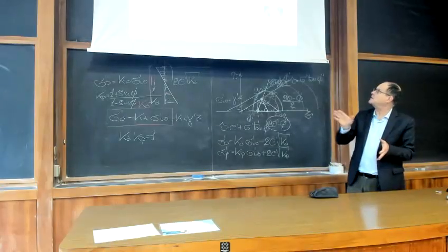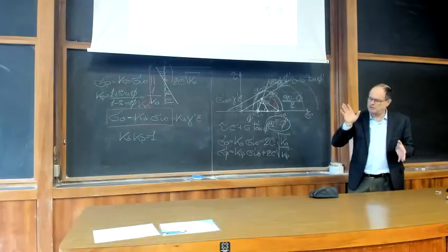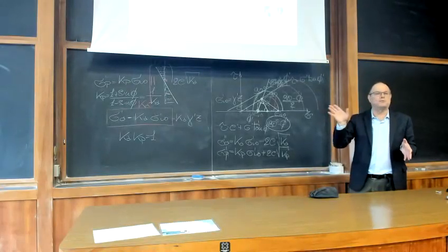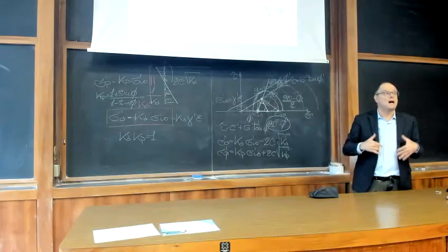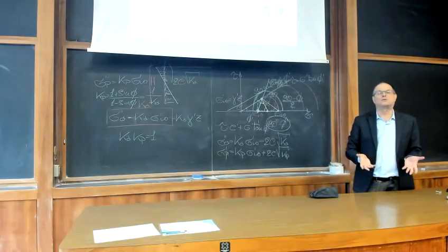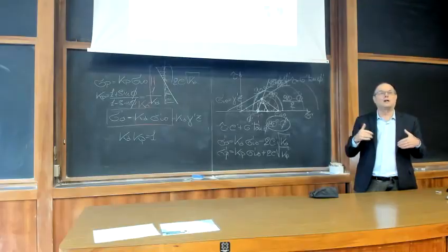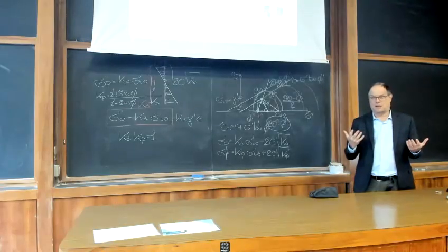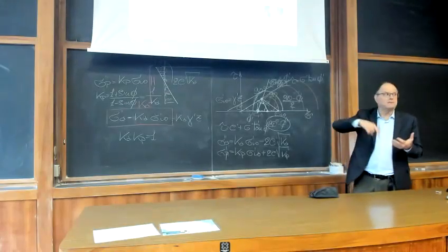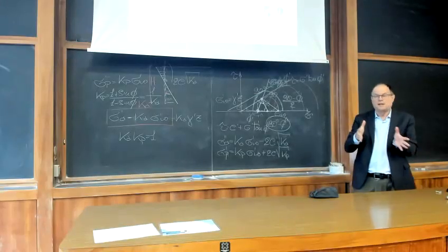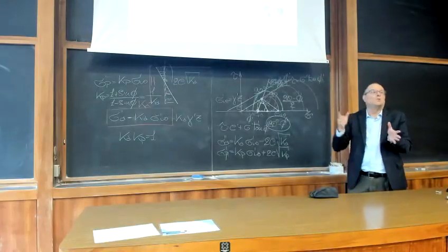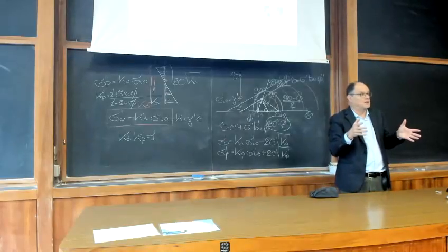So you generate a centrifugal force, and you enhance, as we are used to saying, your gravitational field. So you keep spinning all the time, and you generate a stress field in the soil which is increased, enhanced.